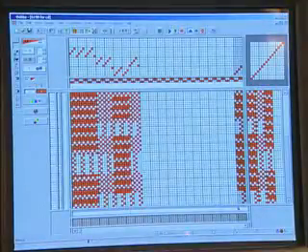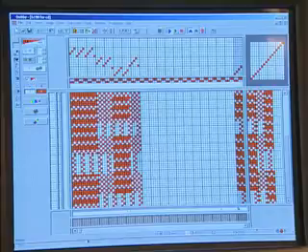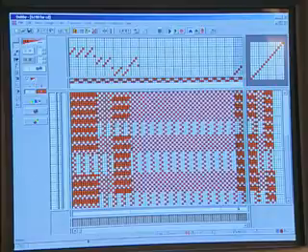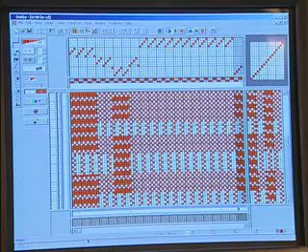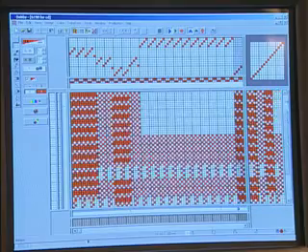Once the weave has been determined, the design can be entered into the computer. A technical design is developed and is composed of the elements the weaver uses to construct the fabric. These three fundamental elements are the weave design, the draw-in draft, and the chain plan.